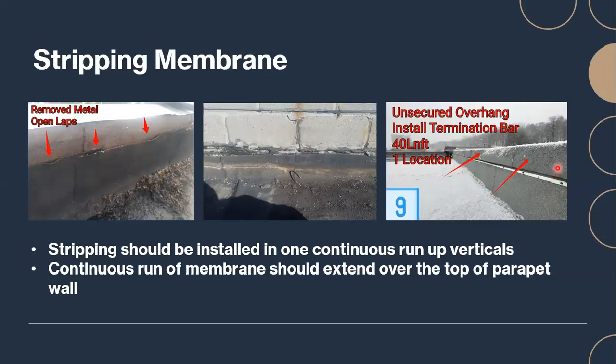However, it isn't to the manufacturer specifications. There's also a termination bar installed here, but it's on the underside of the membrane and isn't fastened to the membrane that's coming over to the top, and therefore isn't really serving much of a purpose.